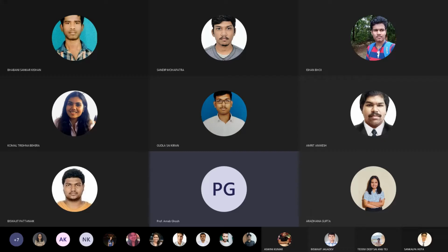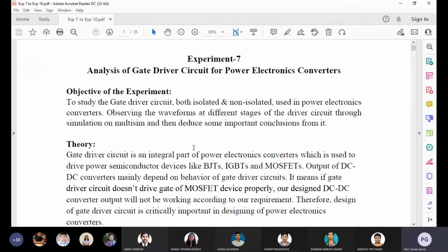It's an almost fixed value, meaning almost a DC value. Then that DC value will be compared with some repeating sequence, or you can say a triangular voltage. After comparing with the triangular voltage, we will directly get some PWM, and that PWM can be fed to your solid state device.